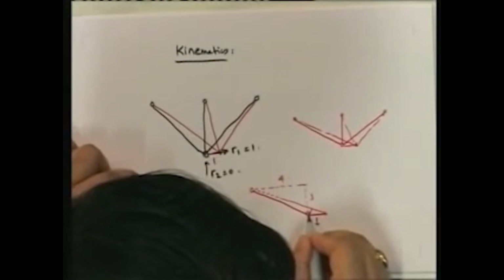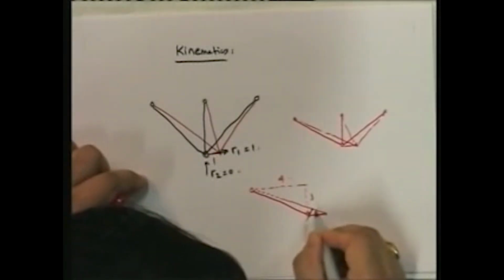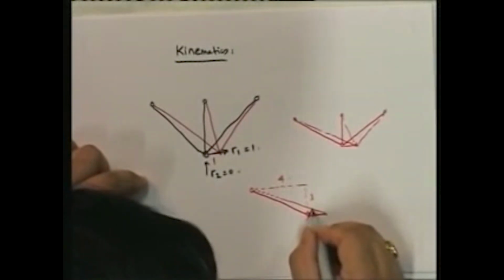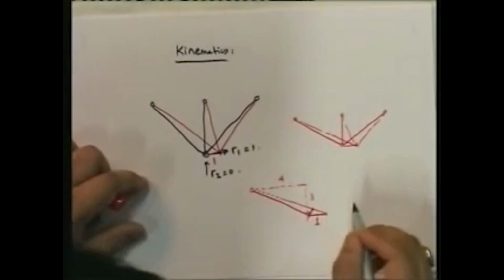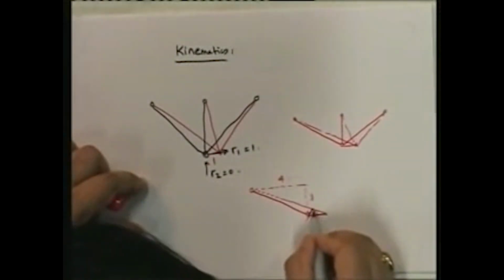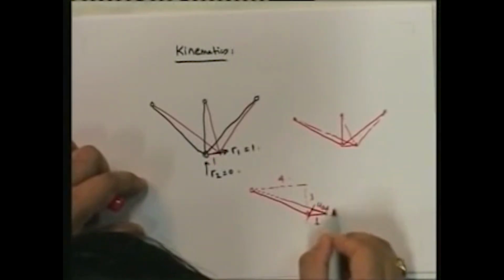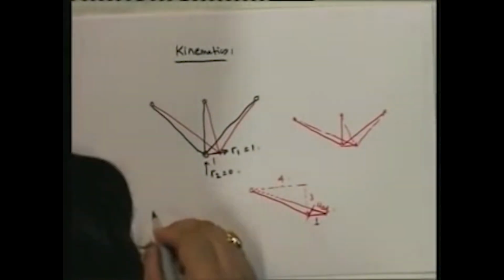To find out the length, what do I do? I drop a 90 degree here, because remember, small displacements, if it goes perpendicular, then there is no change in length. So all I need to do is now find out, if I dropped a perpendicular here, how much this is, and this is going to be my UAD. So how would I find that out? Let's draw it.